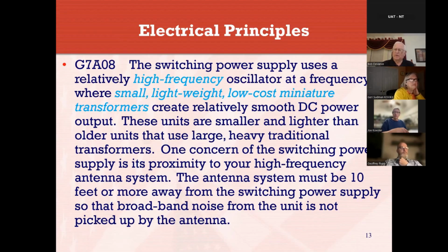The old linear power supplies were huge, very heavy and quite expensive because they used a huge transformer inside to step down the 110 volts AC to somewhere around 12 volts. Then we would go through a rectifying process to convert the AC to 12 volts DC, and then do some serious filtering to make it work. All that made it very heavy, very big, and very expensive.